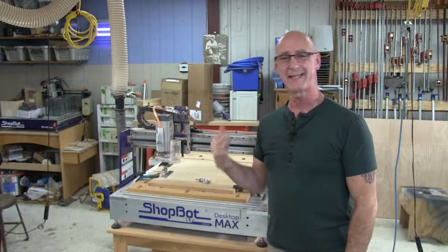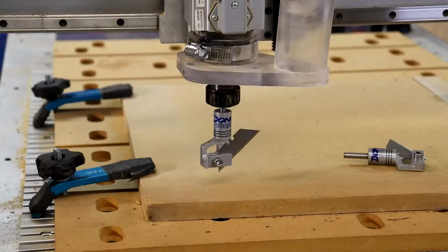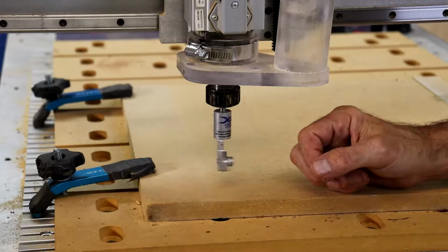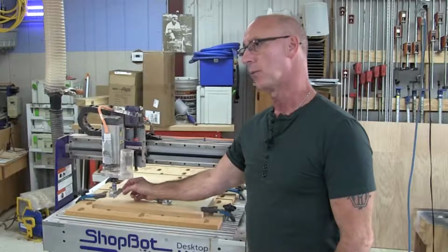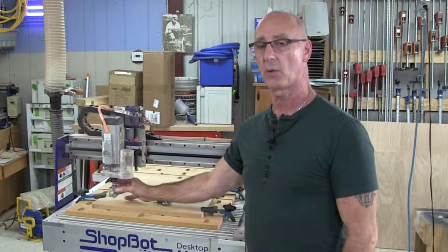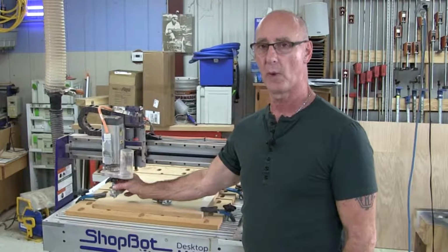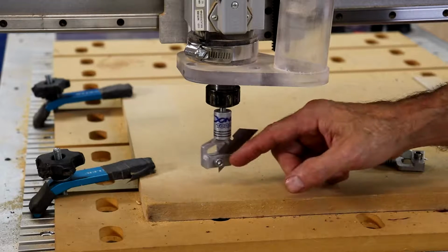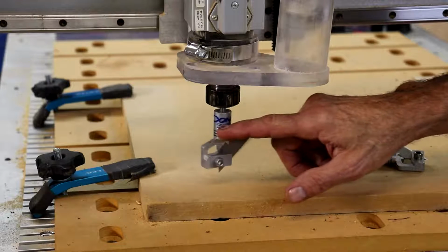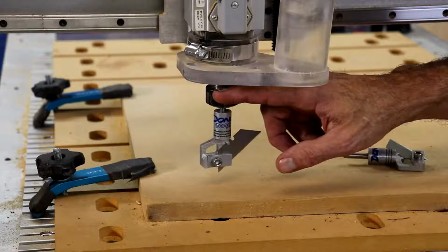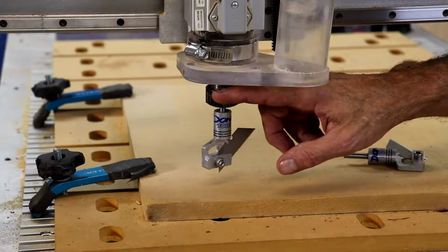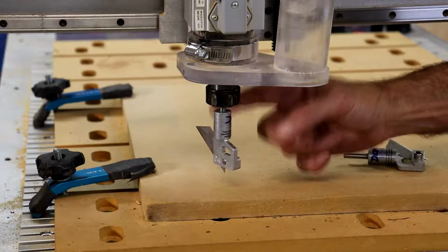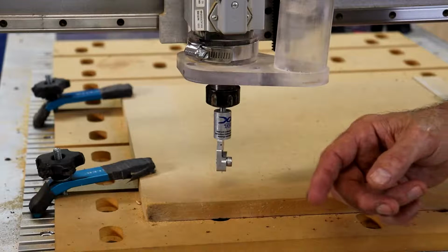I'll be cutting leather with a Donic drag knife on the CNC, and I've got one in the spindle now so you can understand how this works. Really critical that the spindle or router must be turned off when you use a drag knife. Now what's going to happen here is that when I spin this, that's bearings in the knife turning. That is not the spindle of the router turning. I'm not turning the collet. This is on its own bearings.